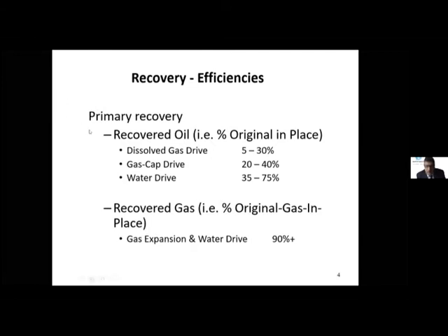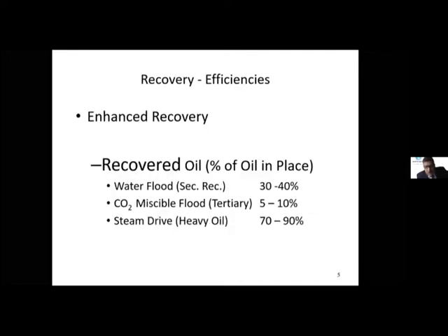So we have primary, and that's from nature. We have the gas also could be recovered as well by same principle of drive mechanism. Most of the gas field, they have a very high recovery factor up to 90%. But oil fields, they don't have recovery factor, maximum 75%. That's maximum. But most of the time, they could be 40 to 50%. So the oil will be left behind, need to be recovered. I need to get it out.